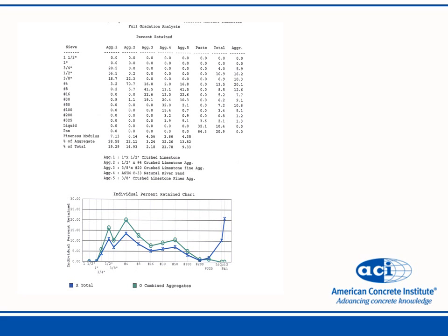Then I would give a percent retained gradation so that they would start looking at the percent retained, because there are many things out there to study the aggregates, because we do not want two peaks. We want a design where the aggregates is like a slide. You go up the steps and then you slide down. That's what we want with our percent retained, or a haystack, what we're looking for. We do not want two peaks.